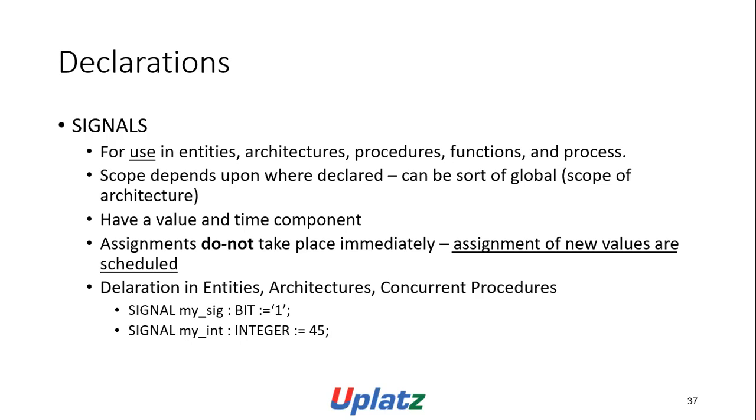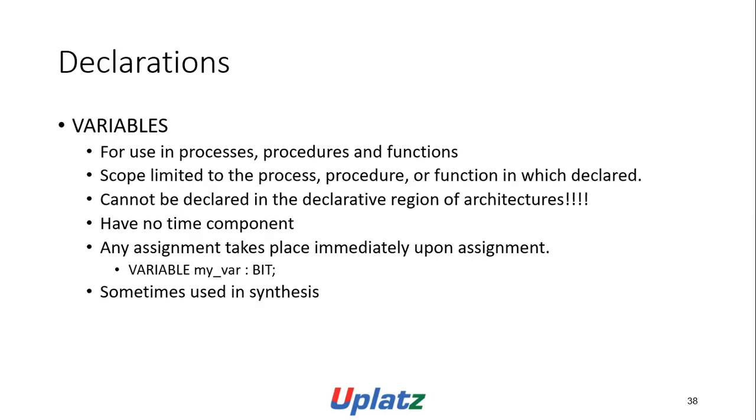Declaration in entities, architectures, and concurrent processes. Signal SIG of type bit is equal to 1. Signal of type integer is equal to 45.